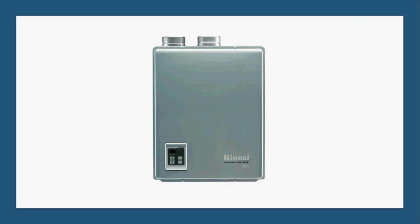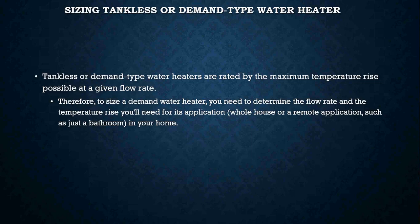This particular one is a gas fired, high efficiency, on-demand water heater. Your tankless or demand type water heaters are rated by the maximum temperature rise possible at a given flow rate. So when we are sizing a demand water heater, you need to determine the flow rate and the temperature rise you'll need for a specific application.